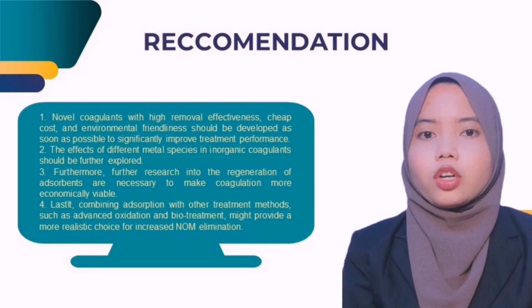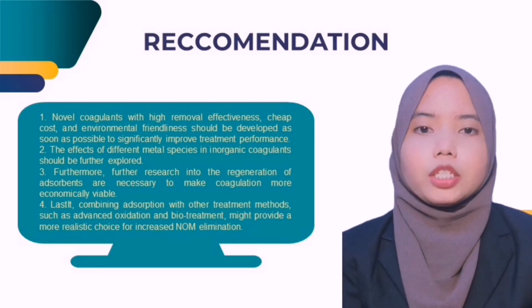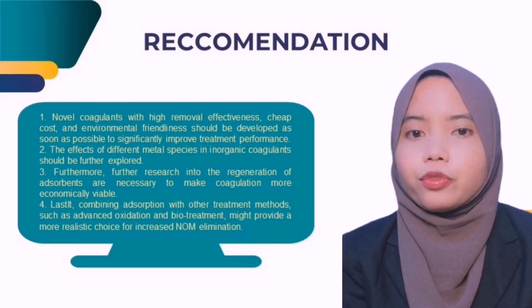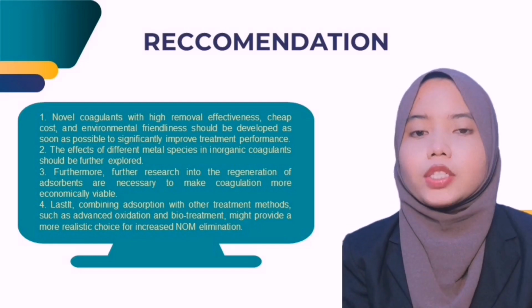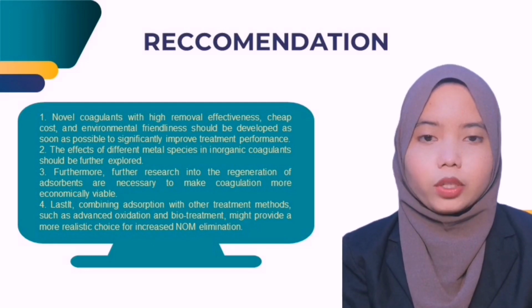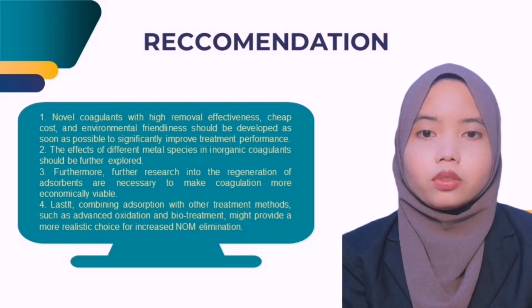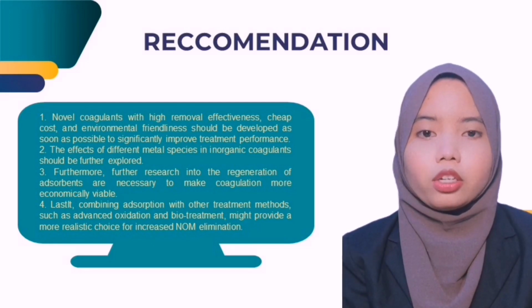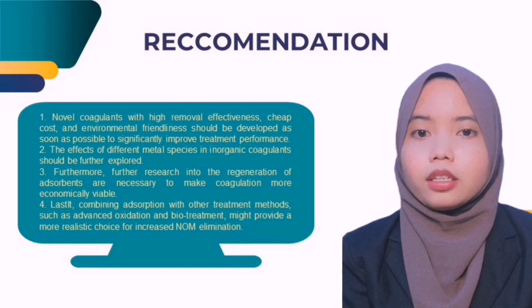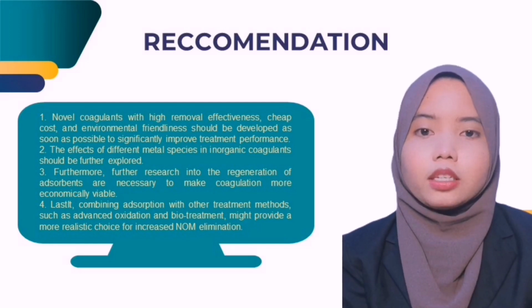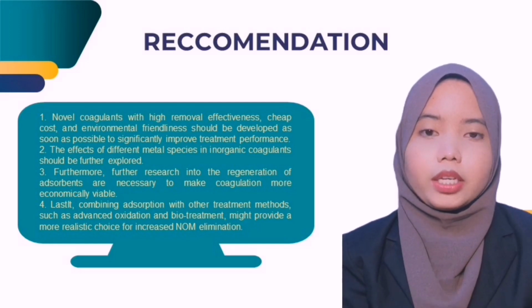Recommendation. Firstly, novel coagulant with high removal effectiveness, cheap cost, and environmental friendliness should be developed as soon as possible to significantly improve treatment performance. Second, the effects of different metal species in inorganic coagulants should be further explored. Third, further research into the regeneration of adsorbents is necessary to make coagulation more economically viable. And lastly, combining adsorption with other treatment methods such as advanced oxidation and biotreatment might provide a more realistic choice for increased natural organic matter elimination.